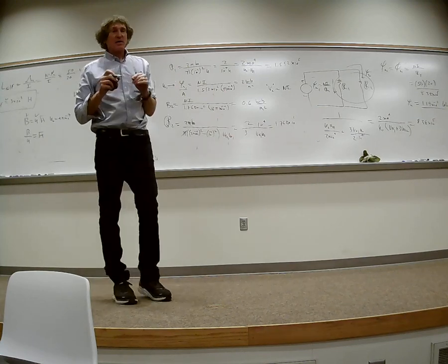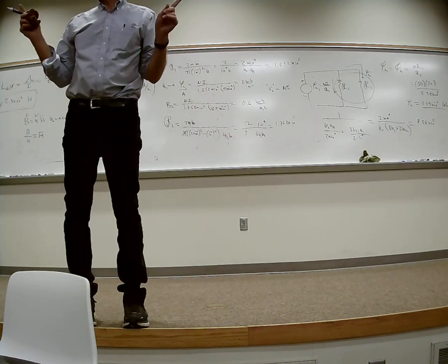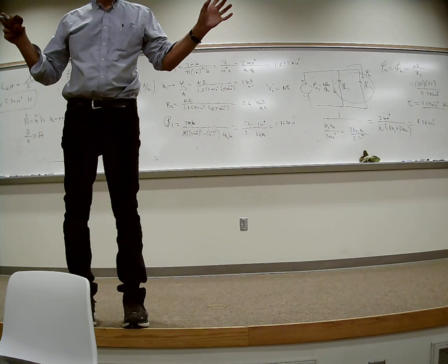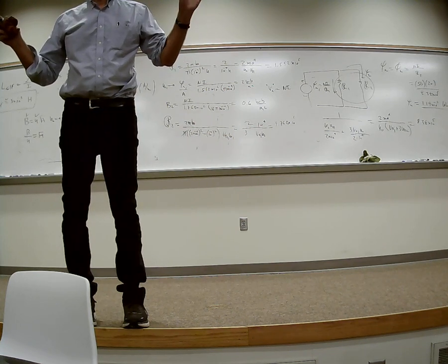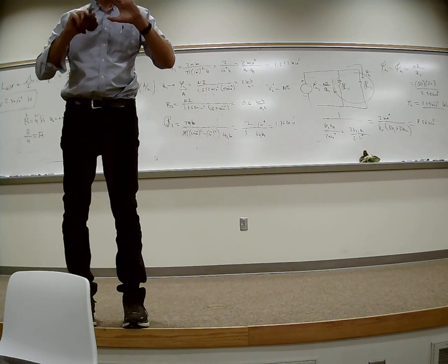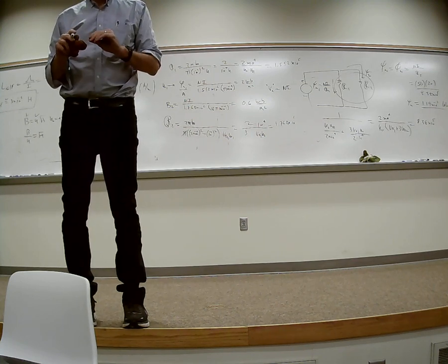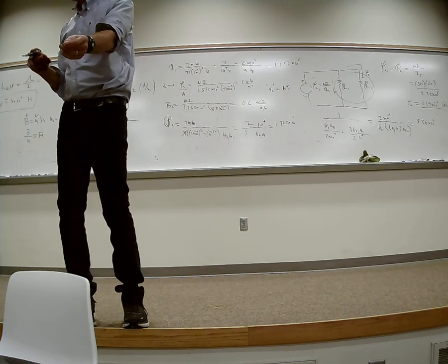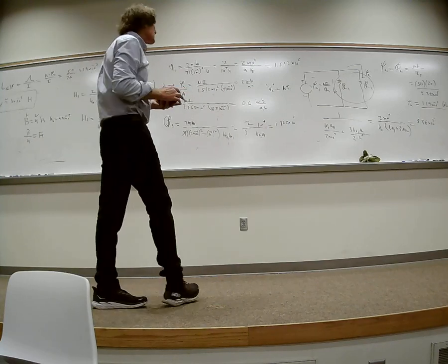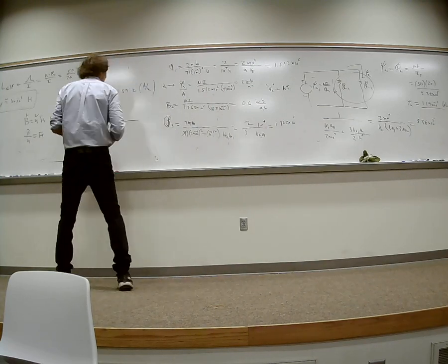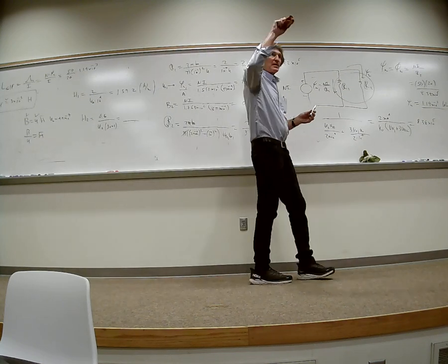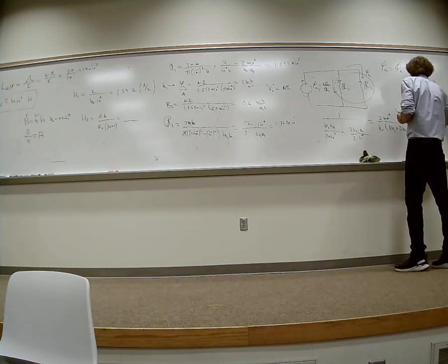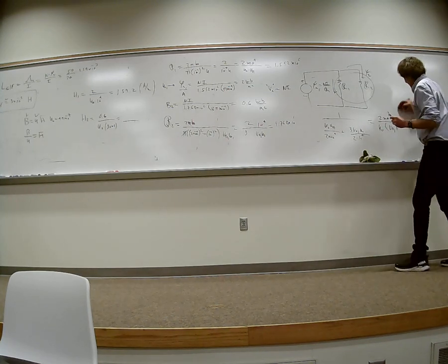It has to be. Something else, just think to yourself. You know how the integral of E dot dl is the voltage? Remember that. If you just take E times L, if the E field doesn't change and it's in the direction of L, E times L would be the electrical voltage, right? Now, the magnetic voltage is like N times I. Didn't I just say that? So, if you take the total length you go around, which is 2 pi times the mean radius, times the H field, you'll get Ni.